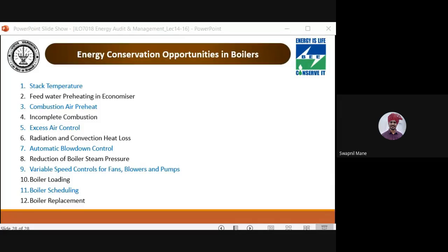Okay, but putting oxygen sensors can be costly. So you can put a flue gas analyzer which can analyze the content of oxygen at the end of the combustion. That will also give you a clear idea of the amount of oxygen being used for complete combustion. Okay, so you can use the oxygen sensor at the initial part of the boiler in the air preheater portion, or you can use a flue gas analyzer at the end of the boiler in the flue gas section.